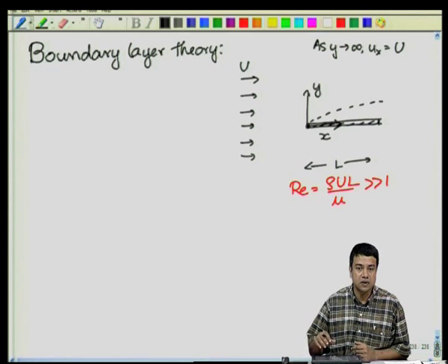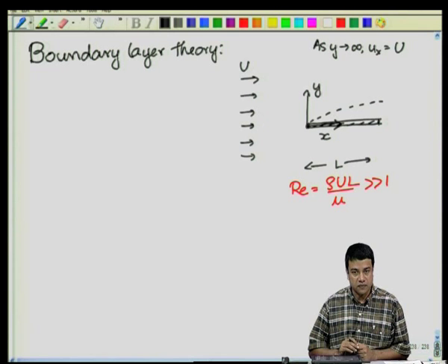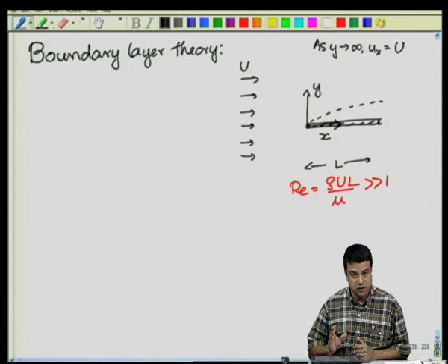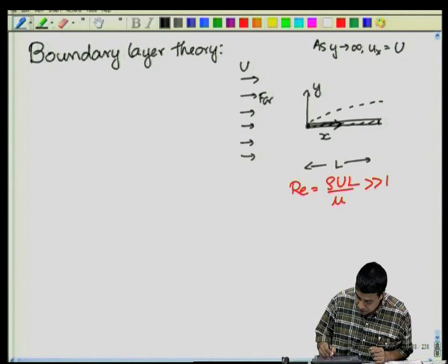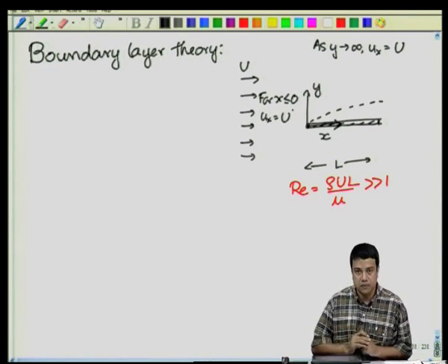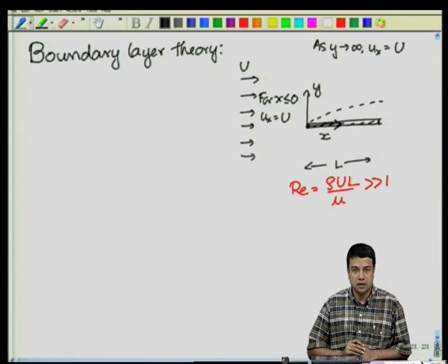That is basically what this high Reynolds number condition means. So, if you neglect streamwise diffusion, and we have done that in the last class based on physical considerations, then the velocity of the fluid before the leading edge of the plate also has to be the free stream velocity. So, you require that for x less than or equal to 0, ux is equal to capital U.